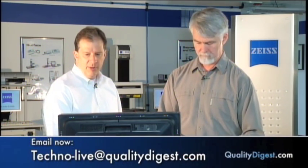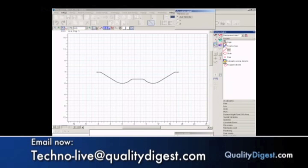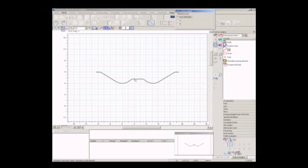So in here I have a few features that we're going to use today. One feature that I might want to start with is create a line. And the first thing I might want to do is put a line in this flat right here, because that might be my datum on this part. Sure. And I want to level the part, or level the trace, to that datum. So I'm going to just give it, with clicks on the screen, a range of data to fit a line to.